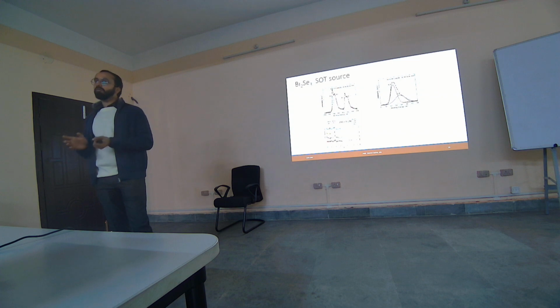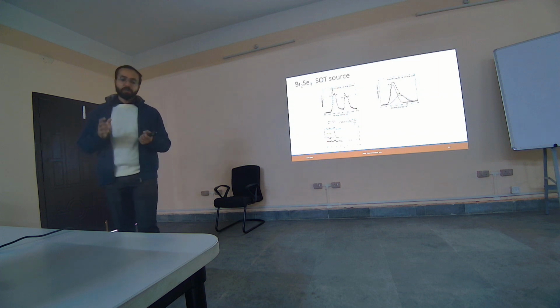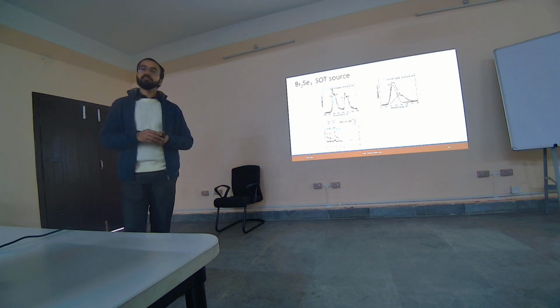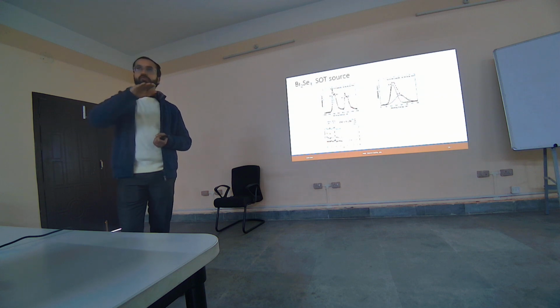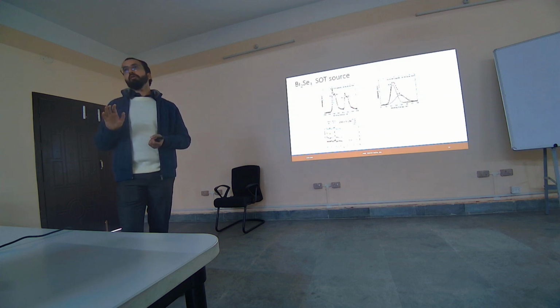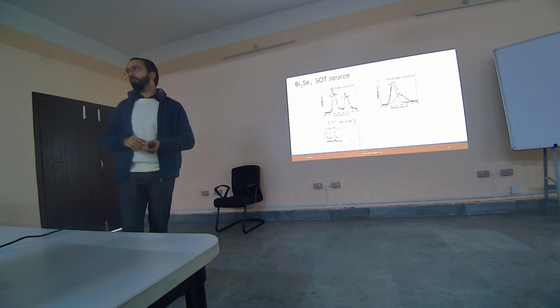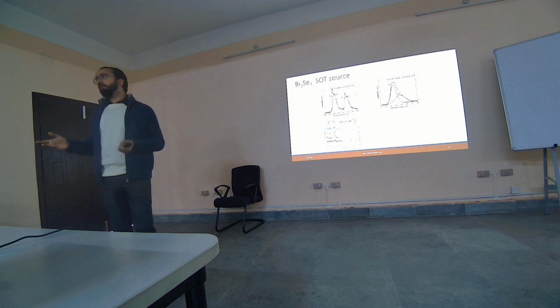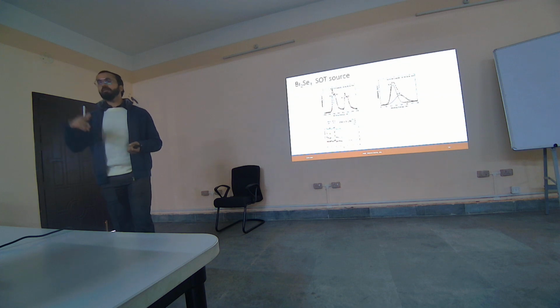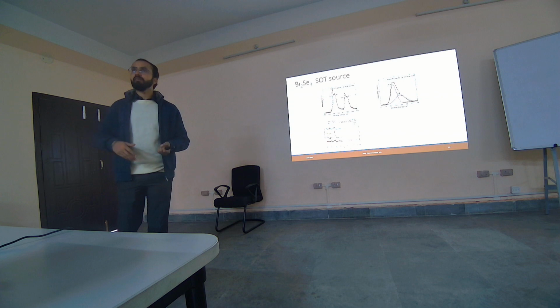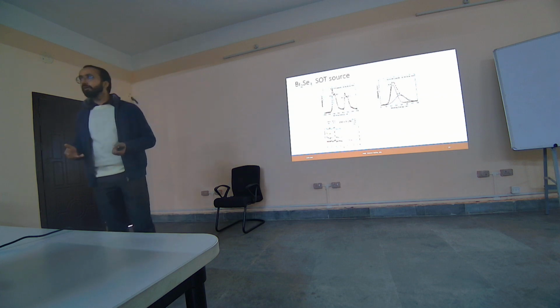Some of you may have heard of it, some of you may not, but it's called molecular beam epitaxy. This will enable you to grow very smooth films layer by layer, but it is super expensive and super time consuming, and industry doesn't like these kinds of processes because who has the money and patience for that? They would rather put 10 more factory lines and make something which is faster, right?